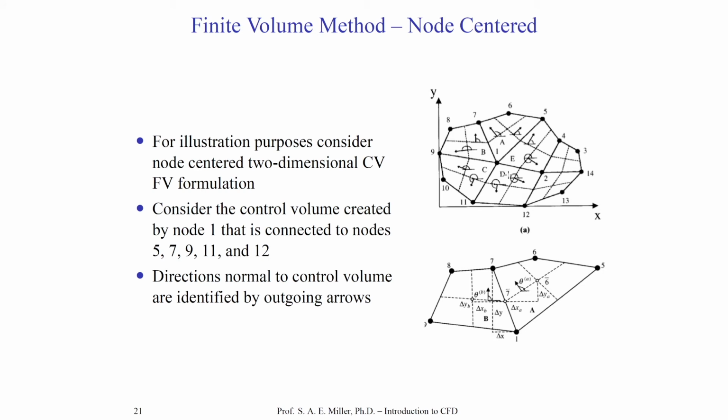You can see another wonderful thing about the finite volume approach is that there's no restriction on the number of faces or sizes or shapes of the elements. It is good to have a well-made computational domain for a well-behaved solution, but these types of formulations are going to guarantee that you can create a system of equations that is simple, and you don't have to do a lot of extra programming and mathematics like in the finite element method to handle these arbitrary element shapes and their transforms. There's none of that involved. What a wonderful thing. But of course, all the simplicity will come at a cost, as we'll discuss later.